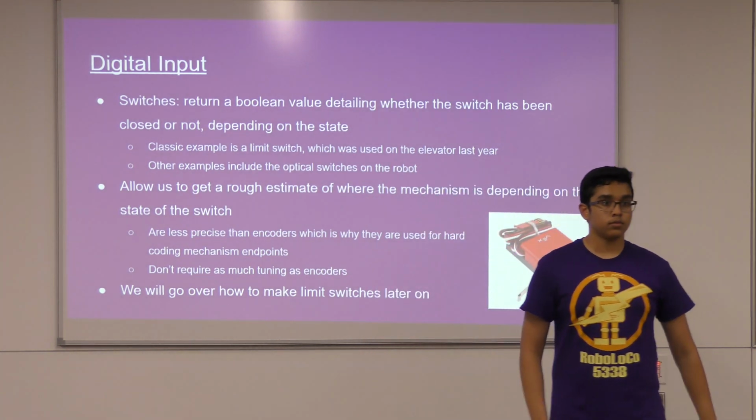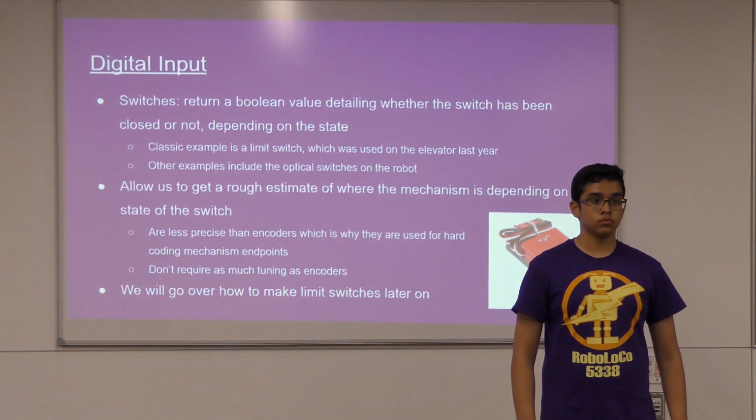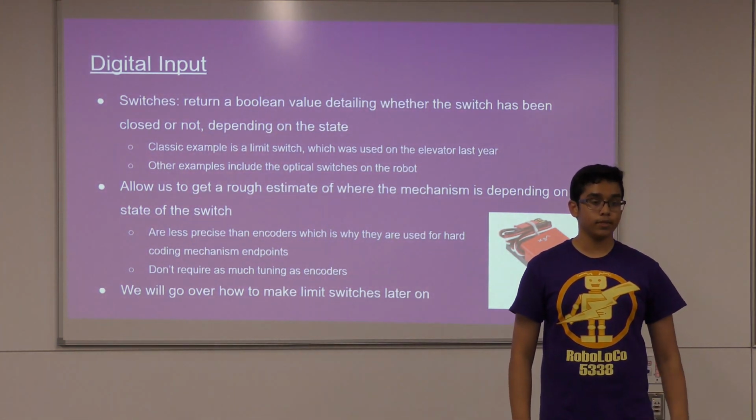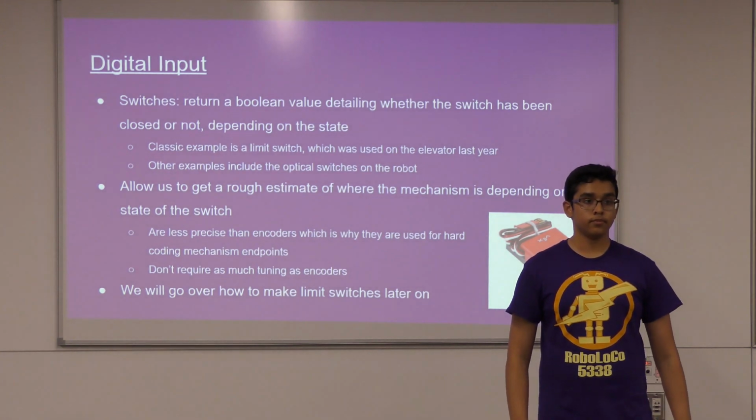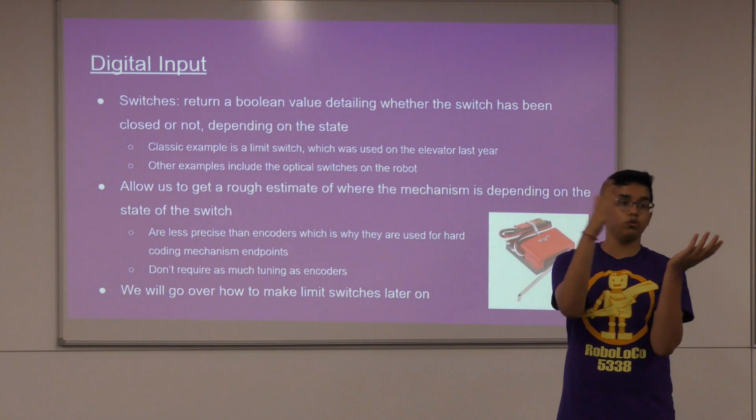You could also use a switch as potentially a signal to zero your encoder, right? Yep. If you know your position, you hit the switch, you say zero your encoder, and you know where your encoder is. And then you do minute changes from there.